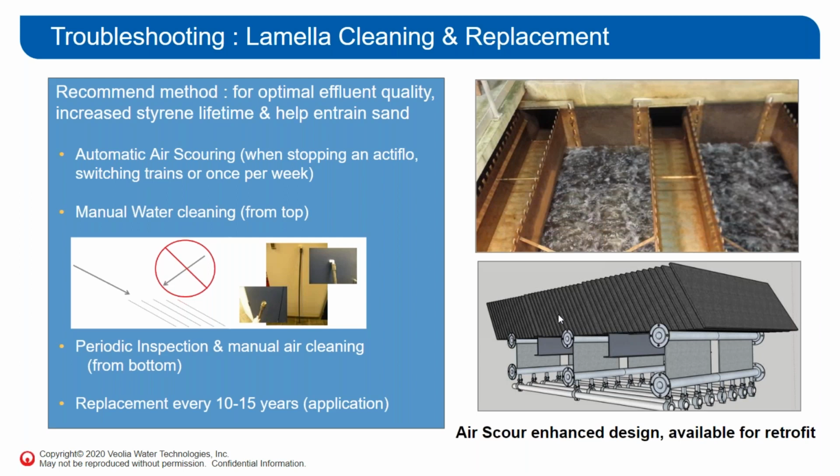And if you can keep that clean, it's not only going to save you from adding sand, but it's going to help your effluent. So in the end, a capital investment of an automatic air scour isn't the worst way to go if it saves you man hours and sand, and it saves whatever's downflow of your Actiflo, even if it's just a river or lake that has a buildup of dust or micro sand.